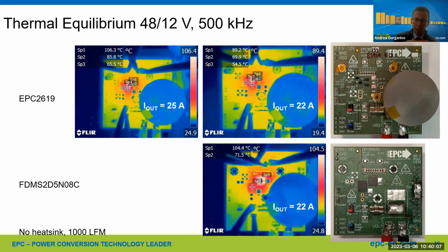The minimum, the best you can do, is going to be lower losses, probably in most cases, maybe except at a few kilohertz, because you have a bigger figure of merit. And this minimum is also shifted to a smaller device and a higher frequency. So those are all things that play to the advantage of GaN.